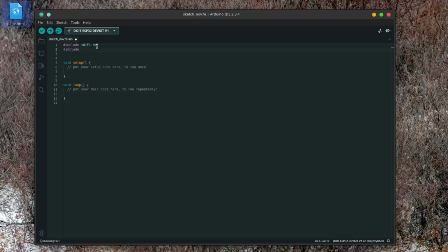These two libraries help us facilitate communication with the ESP32. So the ESPAsyncWebServer library helps us create a simple asynchronous web server on our ESP32 that can intercept incoming HTTP requests and handle them to do the required tasks.